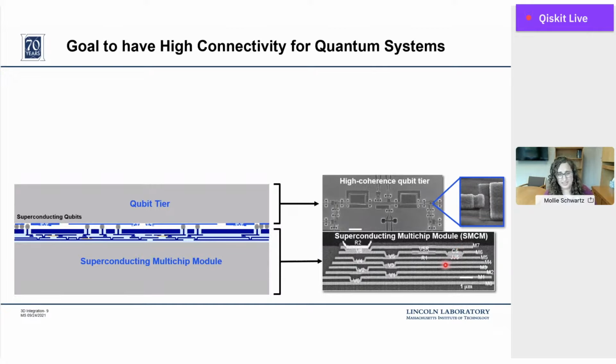The trouble with this is that the dielectrics that we use to achieve this really nice planarization and really high yield are really death to the qubits. So the dielectrics will interact with the qubits. They will ask the qubit, what is your state? What is your phase? And the qubit will answer them. And as the qubit answers the dielectric, it loses the information to that environment.